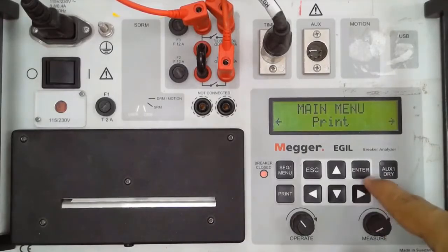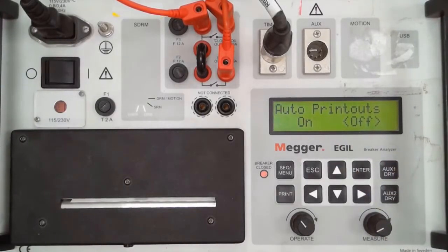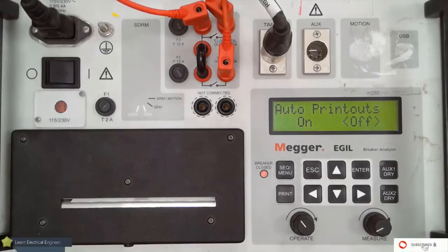I will move on to the second thing I have, which is the print. Regarding the print, it asks if you want an auto printout that follows the report automatically after you finish your test, on or off. Normally you would turn it on, but in our stations, when I turn it on and, for example, I have a problem with the connection or any issues, I end up wasting a lot of paper due to the prints I keep making. Therefore, it's preferable to turn it off. After you execute your test, ensure everything is fine and verify the test results through the device itself, as we will see now, you can then do a manual print.